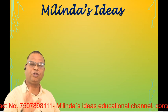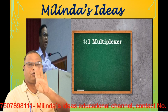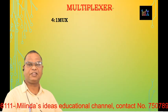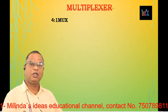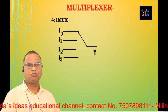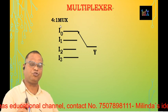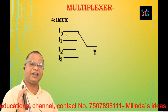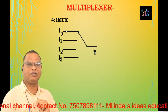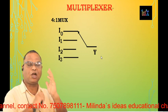Friends, in today's video lecture we are going to study the next type of multiplexer, that is 4:1 mux. In 4:1 mux there are 4 inputs and 1 output, and the simple multiplexing action is obtained by using a rotary switch. In this case we have to use a single pole 4-way switch, and the input signals are connected to those 4 ways, that is I0, I1, I2 and I3. These are the inputs and Y is the output.